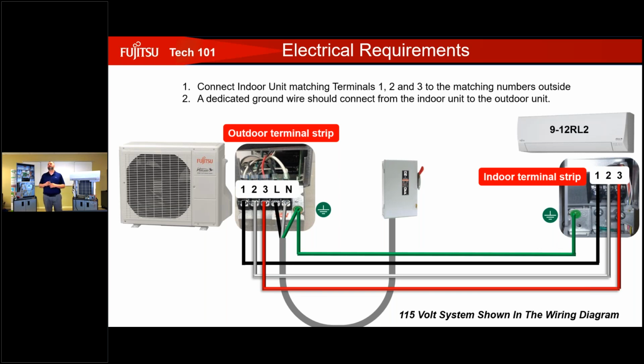Yes, you did allude to this earlier, but we have a question. Do I have to install a switch next to the indoor unit? Yes, I did discuss this. That is going to depend on local codes. We always recommend that you install that switch. It's my recommendation. It's Fujitsu's recommendation. It's Jim's recommendation.